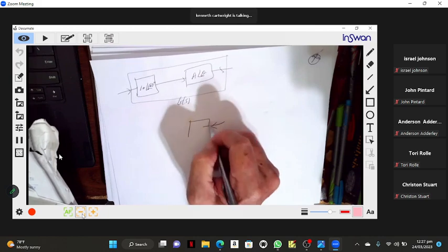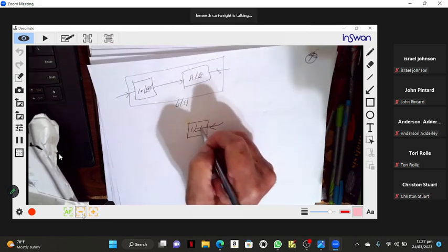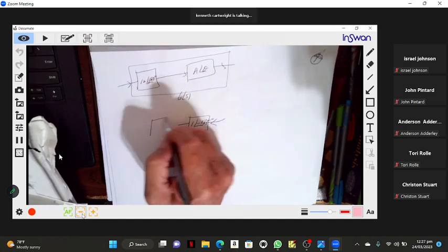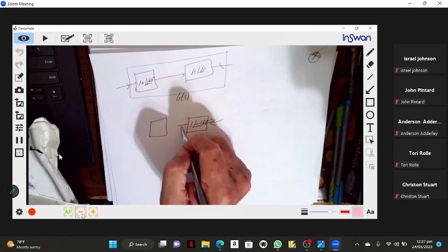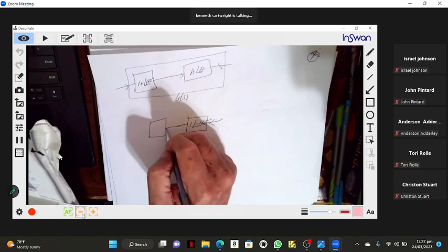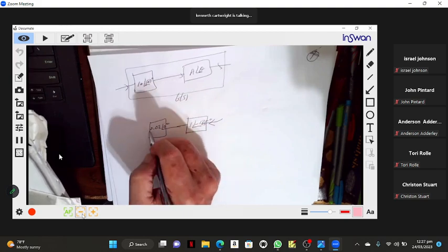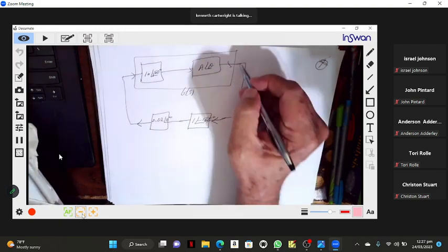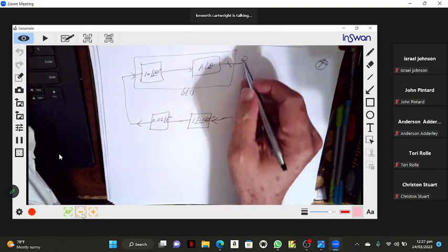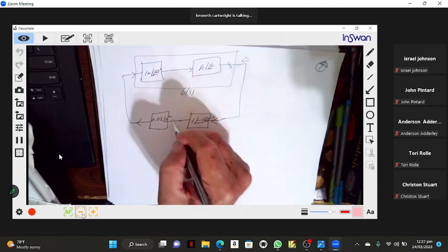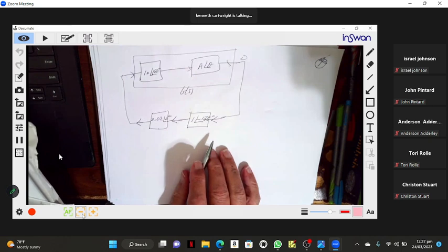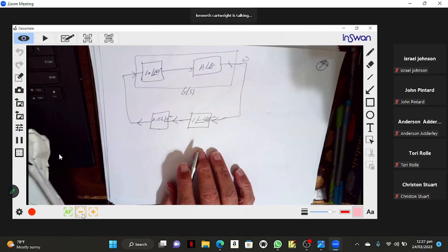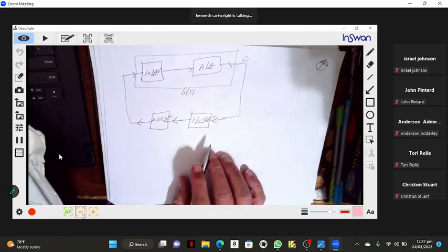So coming in here, 1 at negative 135, and then 0.02 at 0 degrees. And then that's fed back into the input. All right. So this output is fed through this device, and then this device, and then back to the input. And the question becomes, what must A and theta be for oscillation?